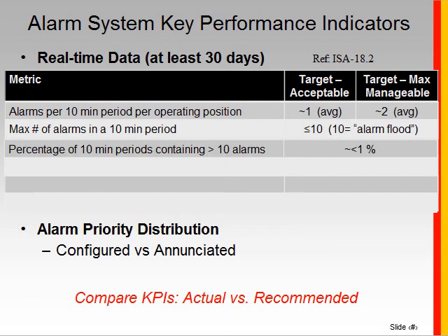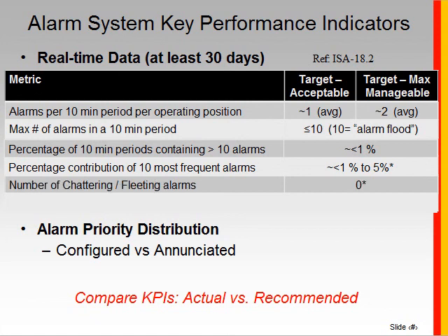So how many alarms occur when a flood occurs, how many are actually being presented to the operator, what's the percentage of time that the system is in flood. We want to minimize the contribution of the most frequent alarms, because they're typically going to cloud the operator's view.